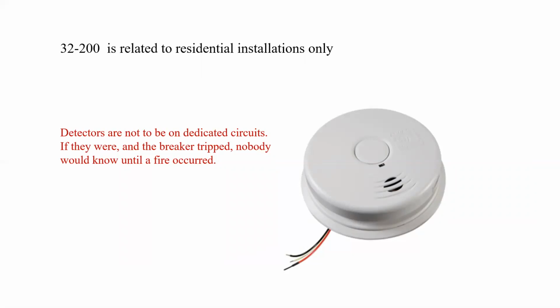residential dwelling would typically even know because no one walks around their house looking for the slight intermittent blink of the red LED in a functioning fire detector. And so, if a fire were to occur, the detectors would be completely inoperable. Instead, we want to have these detectors connected onto a circuit that has at least lights, and it is restricted to be on a circuit that has no AFCI, GFCI, or switches upstream in the circuit.